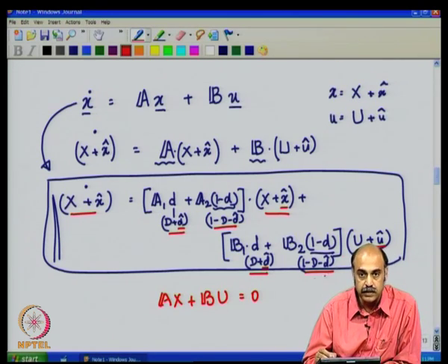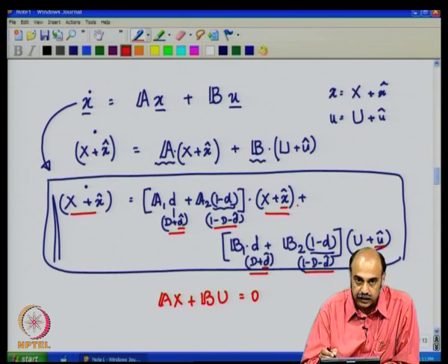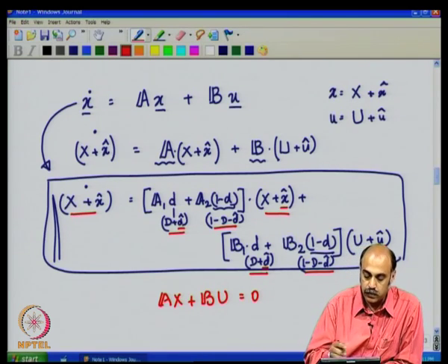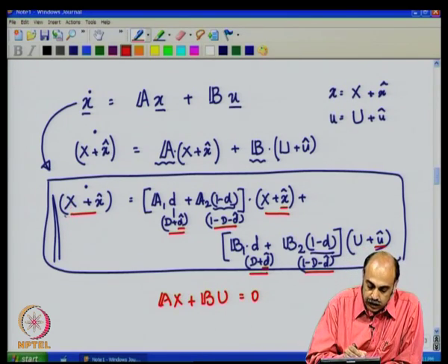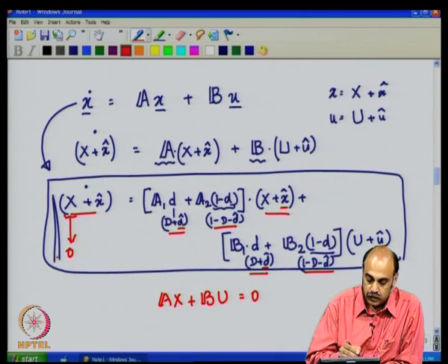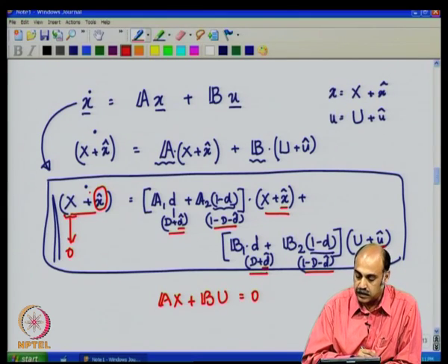After applying this, you multiply component by component, and if there are small signal term multiplications, neglect them, and set the Ax plus Bu terms equal to 0. Uppercase X dot is 0, which means that only this exists on the left hand side.